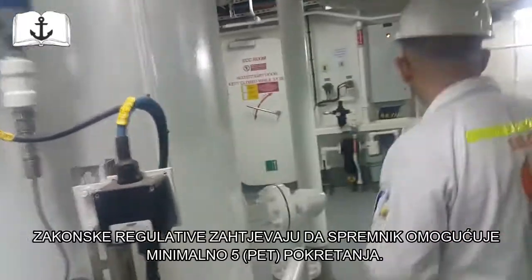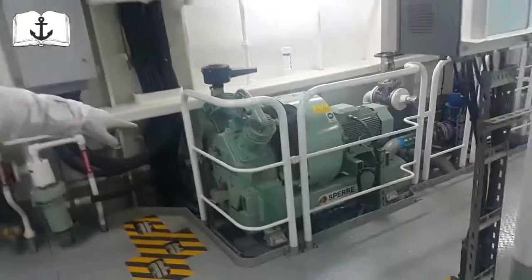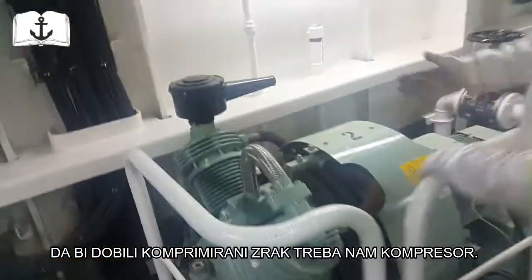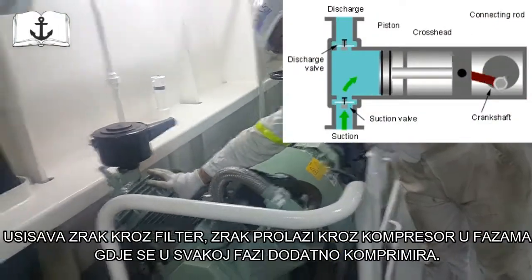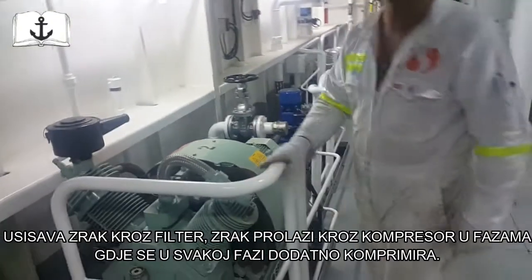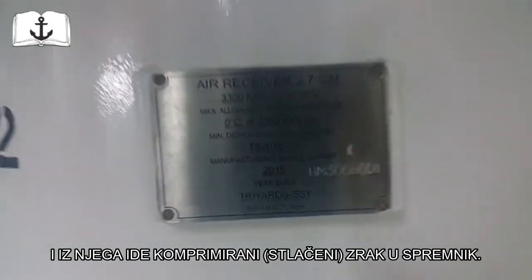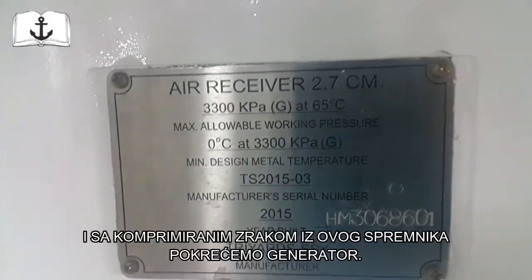Okay. And to get the compressed air, you have the compressor. So this is the compressor, this is how you're getting your compressed air. It's sucking in here through the breather. This is the first stage, low pressure, like 5-6 bar, then going to the high pressure, and it's going to the bottle. So from this compressor, you're charging this one, and with this, you're starting the engine.